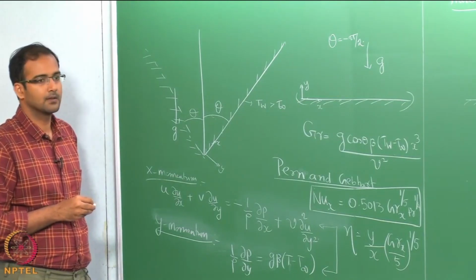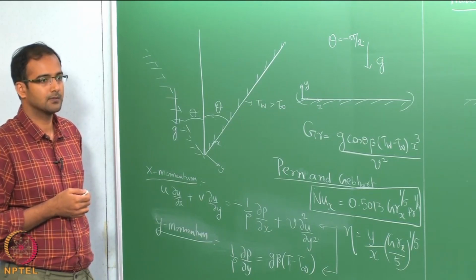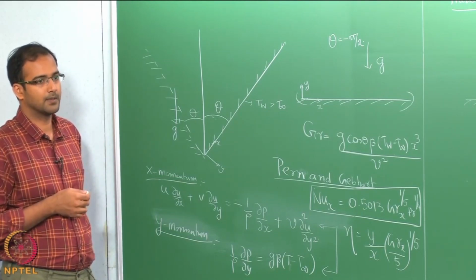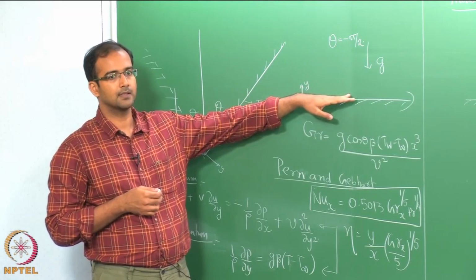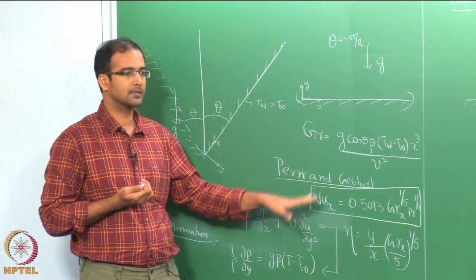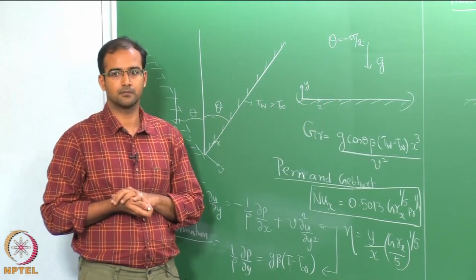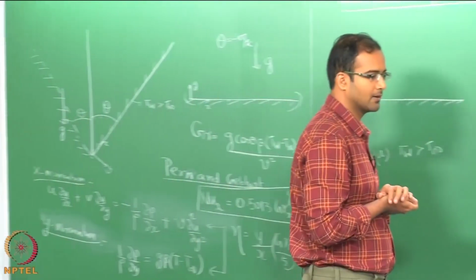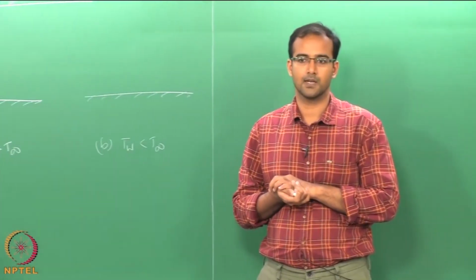Of course, you have to do a finite difference or finite volume method based solution in order to solve this exactly. You cannot neglect also the vertical momentum. There will be some streamline patterns which will rise due to the buoyancy in the vertical direction, and that will definitely cause some vertical momentum. But while deriving the similarity solution, it has been assumed that that is not going to impact the local heat transfer. Okay. So, of course, we have to make some assumption in that case. If you also include the vertical momentum, we cannot find a similarity solution, right.